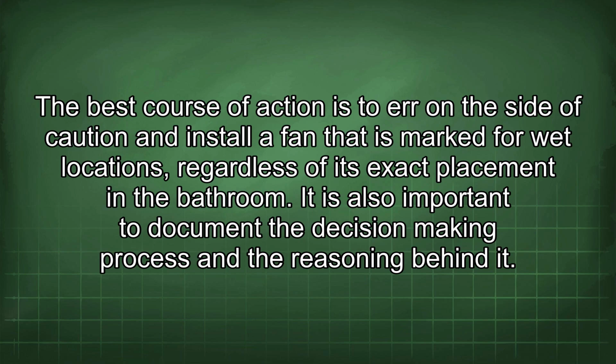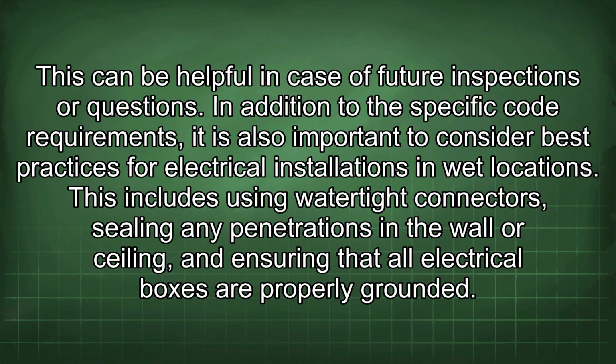The best course of action is to err on the side of caution and install a fan that is marked for wet locations, regardless of its exact placement in the bathroom. It is also important to document the decision-making process and the reasoning behind it. This can be helpful in case of future inspections or questions.